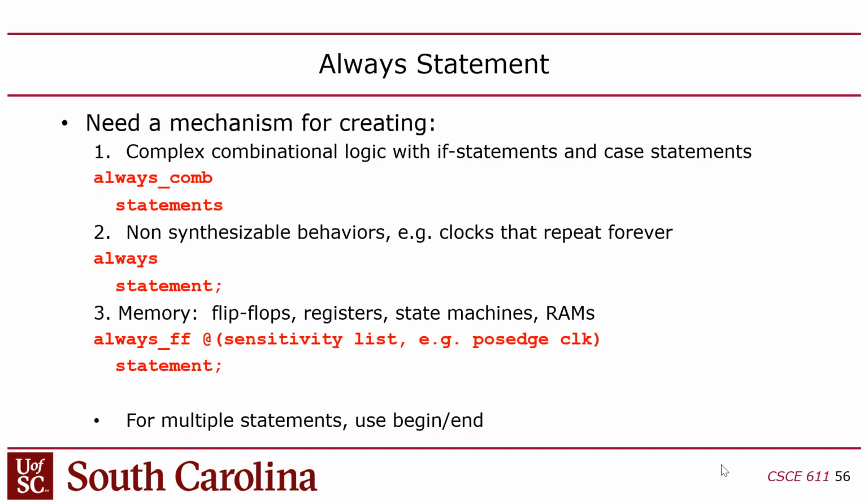So you don't want to use latches. You never want to have latches in an FPGA design. The reason is not because FPGAs can't make latches, because they can. You can implement latches on an FPGA, but it makes timing closure very difficult for the tools. Timing closure, and I have a lecture on this at the end of the semester, is about calculating the critical path logic delay in your whole design, and then ensuring that the clock period is long enough to accommodate that worst case critical path delay, right?